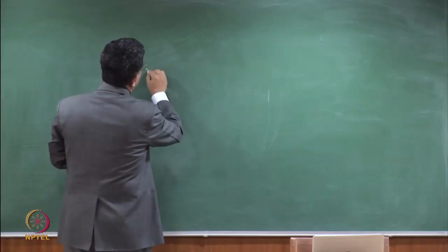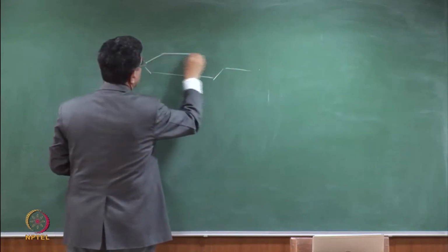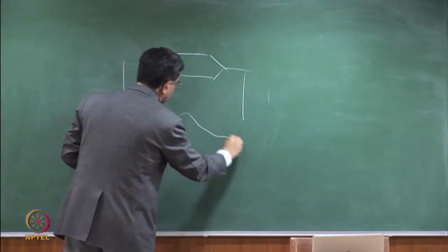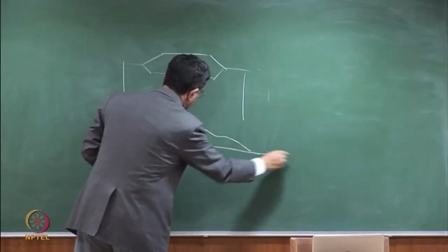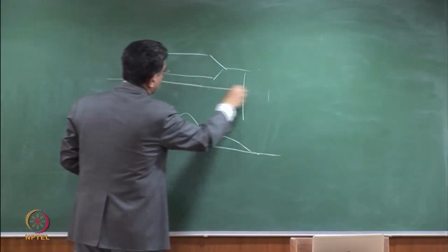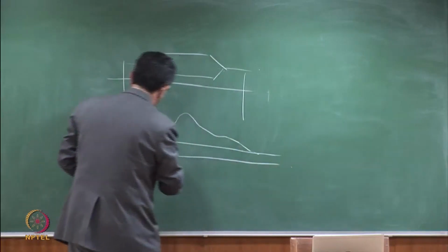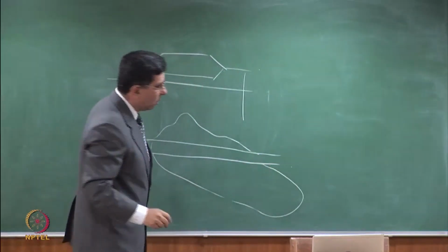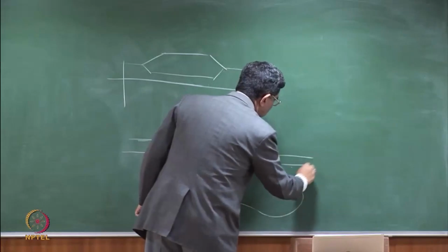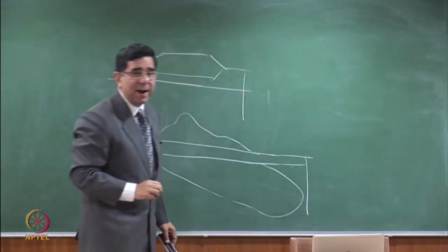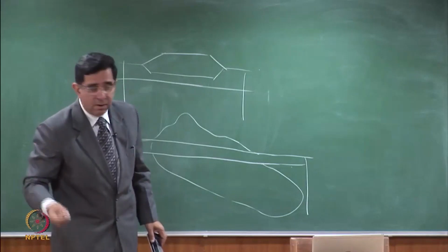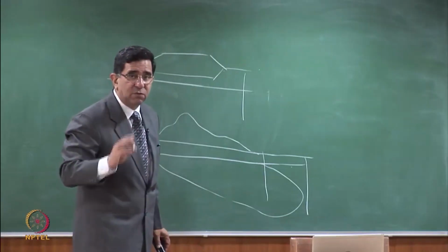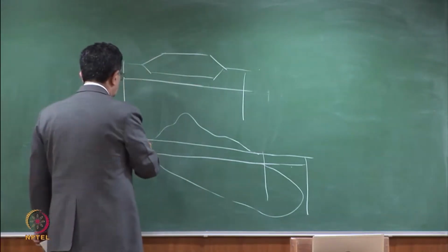So as I said, if I have a new landfill which is well designed, I can monitor here and I can monitor here. But if I have an old dump where the contaminant plume, and say this is the water table, and the contaminant plume over 25 years is like this, my monitoring points have to consider how the plume expands or extends, or how it becomes bigger. If I am going to monitor here, I am going to get the contamination. So in old facilities, find the extent of contamination and then monitor along the boundary.